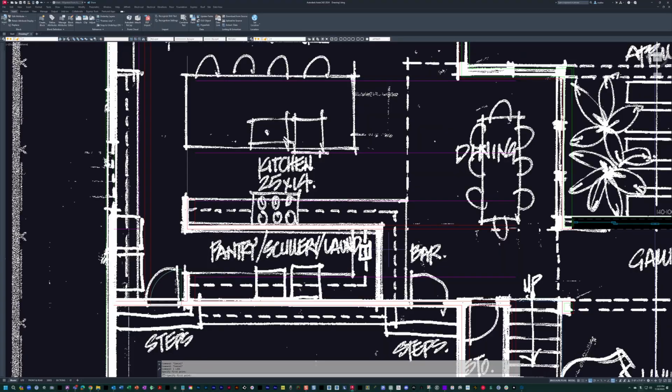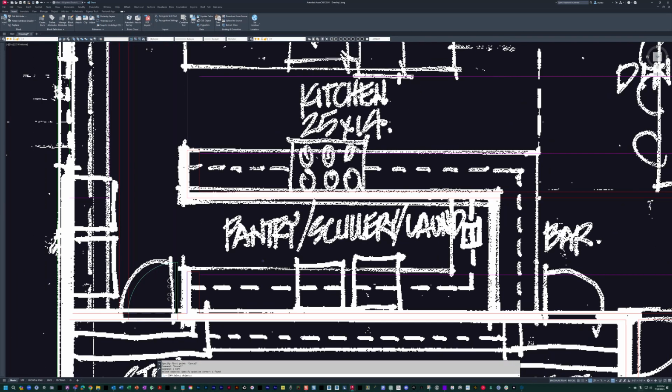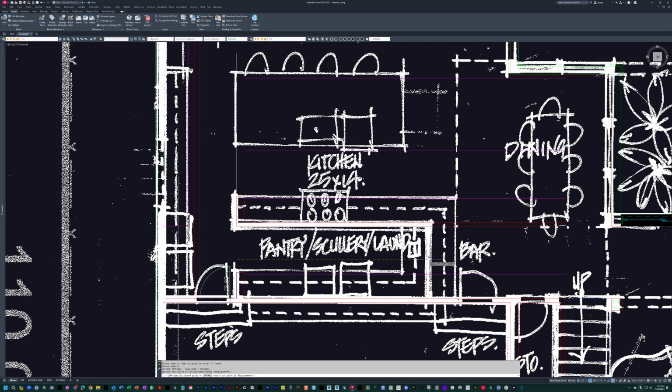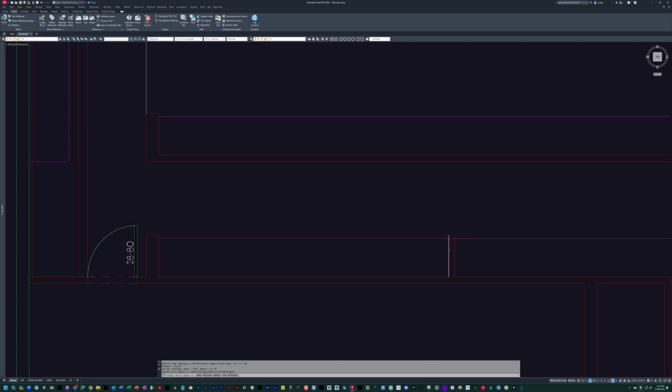Let's create the depth of the pantry. So let's copy this line over, maybe that's 16.4 to there. That sounds like a good number for a placeholder right now. Let's offset 4 inches. So all I'm doing here is we're going to fill it.